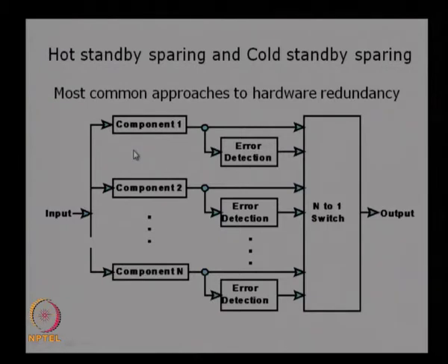All those components are in active mode, and whenever an error is detected, the output is immediately taken from the next one. There is no time delay, because all the outputs are available at any time, and whenever there is an error detected in one of these, the switch will immediately change to the next mode, and the output from the next component will be automatically chosen and given as output. So, there is no time delay, and you always get an output from the system. That is known as hot standby.